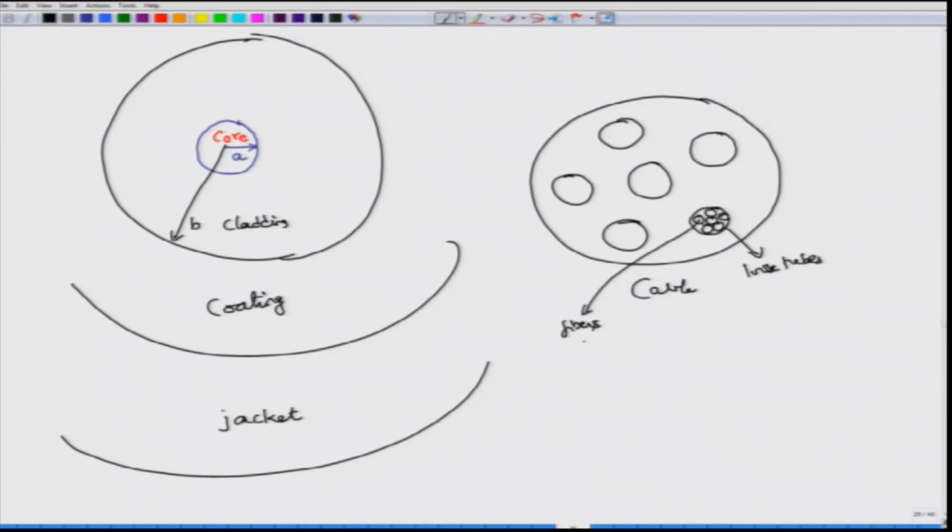Here these fibers just have a core and a cladding. Okay. They do not normally come with the coating, and these loose tubes are also differently colored for visual inspection later on, but this is how an optical fiber cable looks. As I have told you, this is not the only cable design, there are many designs that are possible, and this central member, okay, does not really carry anything. This is just for mechanical support, okay, around which you have this particular cable with typically about 6 of them. Okay. I probably missed one circle, so I am going to put one circle out there.